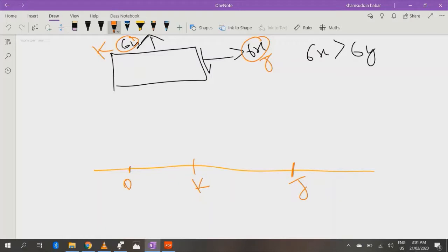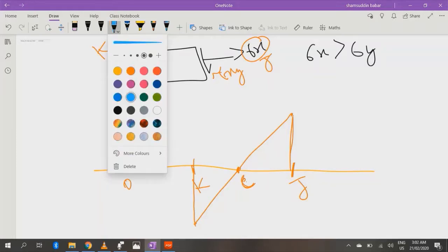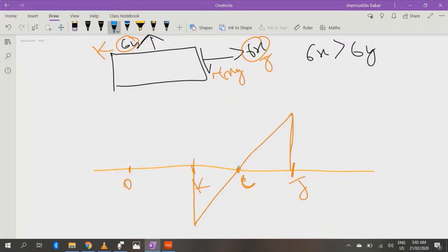Now we know that this is stress XY. So using the stress XY magnitude, draw a perpendicular like this above and a perpendicular like this in the downward direction. Meet both these points at a center C. Now using C as a center, with the radius equal to this, name the points D and E, and draw a Mohr circle.